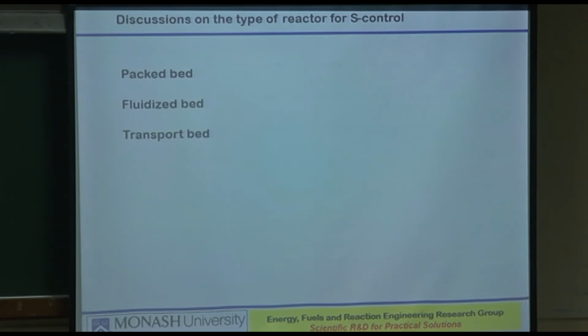And then it has been said that you have to have finer particles which will give you higher specific surface area, because it will be a kinetically controlled chemical reaction. Absolutely right. And that will obviously come at a cost, because the finer particles will give you more pressure drop. But that's fine, as long as it is within acceptable limit, then that pressure drop actually helps you in making the flow from one direction to another.